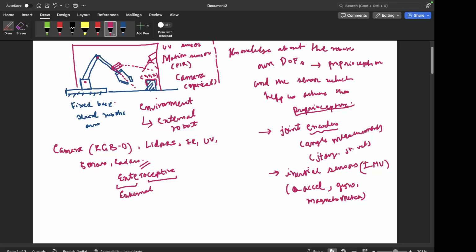It has to be there in the hardware right from the beginning, right? So if you start developing your own robots, then the first thing that you should understand or take a call on is: do you need any proprioceptive sensors, or if you use them, would it help your application? And then first integrate those sensors.